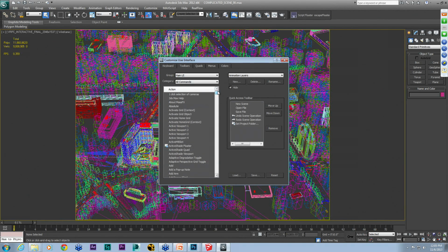One of the things you can do with Deadline is, for Backburner, you can render strips, but if you're doing something with GI, you need to calculate your irradiance first, then send your strips. This may have changed, but at the time I was using Backburner, you couldn't actually render elements in strip mode, like render strips and render elements. It does it now, but it's a pain in the butt. I apologize, this machine doesn't have Deadline on it. You have to make sure elements are out.